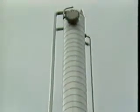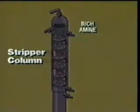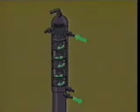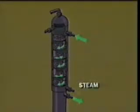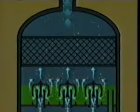Now, this vessel is either a tray column or packed column and operates near atmospheric pressure. The rich amine solution, preheated in the heat exchanger, enters the top of the stripper column and flows downward. The rich amine solution is further heated by incoming steam from the reboiler, flowing upward from the bottom of the stripper column. The heat from the steam helps strip the acid gases from the amine solution. The steam also helps sweep the liberated acid gases out of the stripper column.